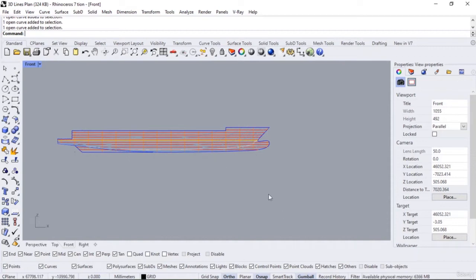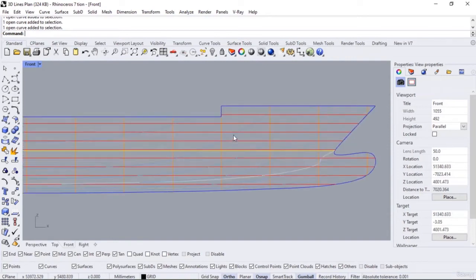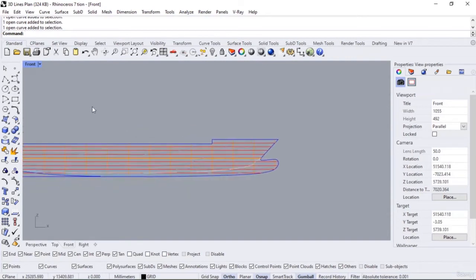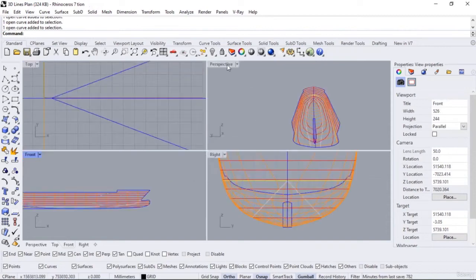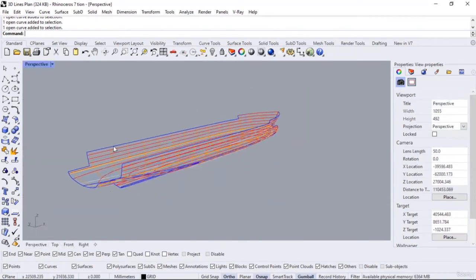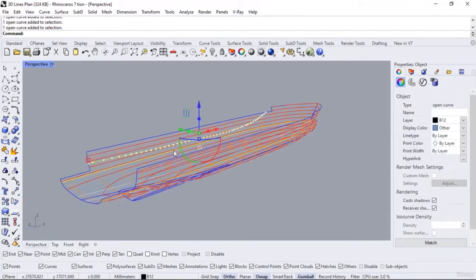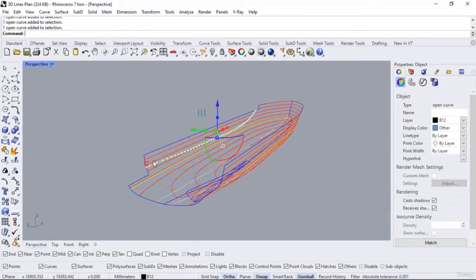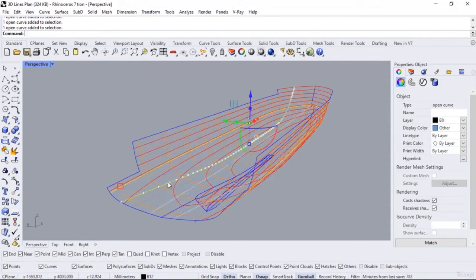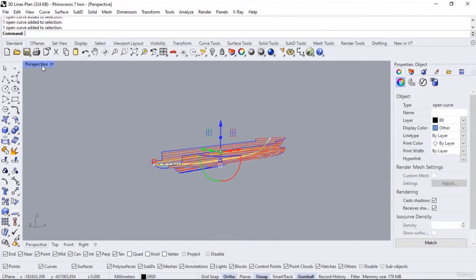So, front apparently has the same curve as here. This is also how the buttocks look here. If you look at the 3-dimensional view, that edge is the blue part. And we can see that the buttocks divide the boat vertically in the fore and aft direction, as we mentioned before. When we look at these from the profile view, they look like this to us.